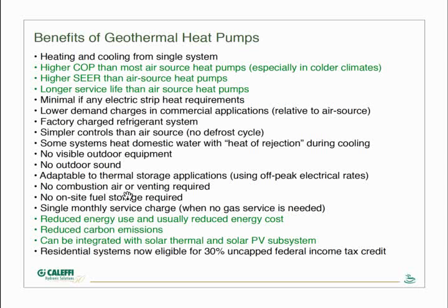But you'll see there's a lot of advantages here with geothermal heat pumps. Things like high performance characteristics, high coefficients of performance, which we'll talk about shortly, longer service life, reduced noise because you don't have an outside unit. It may be an advantage if there's no need to bring gas service to a house. Certainly you're going to save the basic service charge associated with that gas meter. So there's a lot of advantages of using that technology.